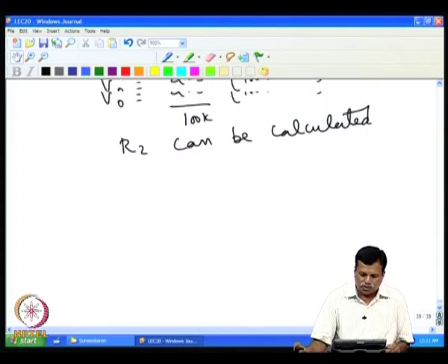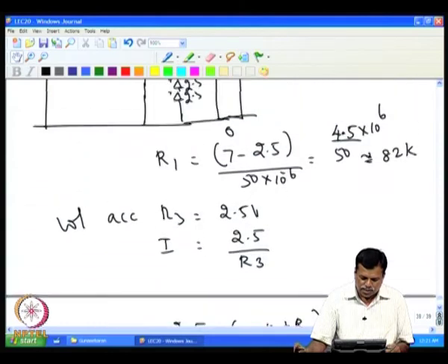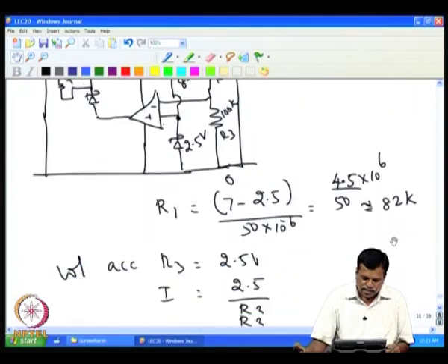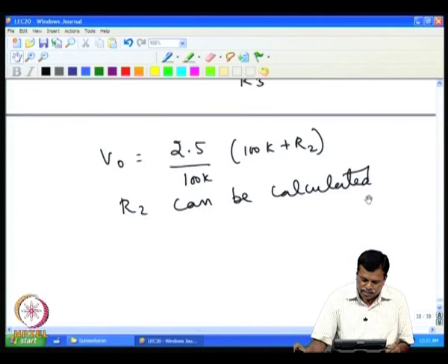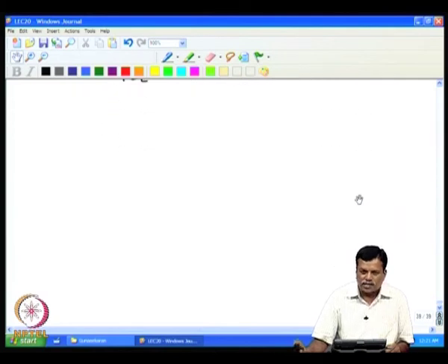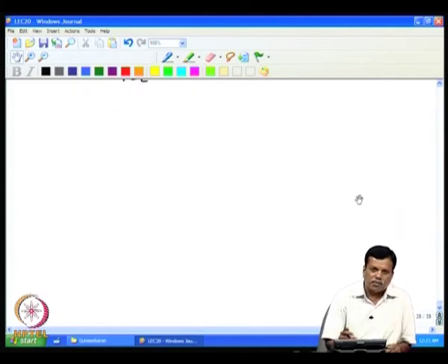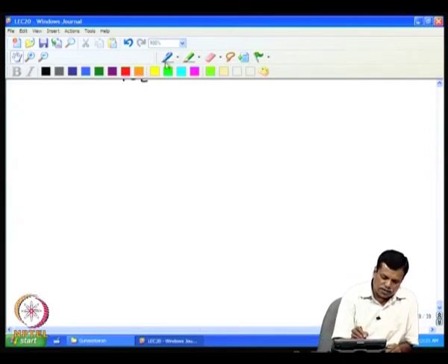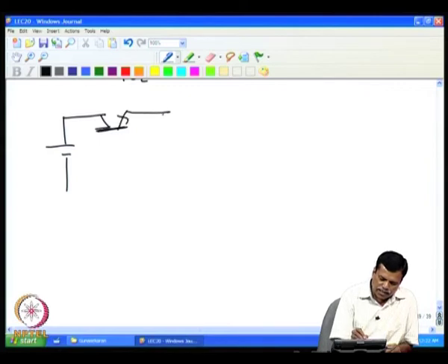Now, from this source, the regulated source, as a basis I will take, and then I will build up the constant current source plus the other circuits to go with the Platinum thermometer temperature sensor. So, we will have now a voltage source, then we had this regulator here. I will skip the other part of the circuit, I will keep only the output here, and then the regulator output is coming here.